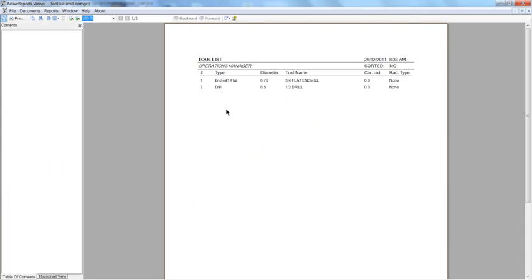The stock is held in a vise on parallels to ensure the end mill does not hit the vise. Here is the tool list. We can see that I will be using two tools to cut the part. A 1-inch flat end mill will be used to cut the steps on the part, and a 1/2-inch drill will be used to drill the holes.